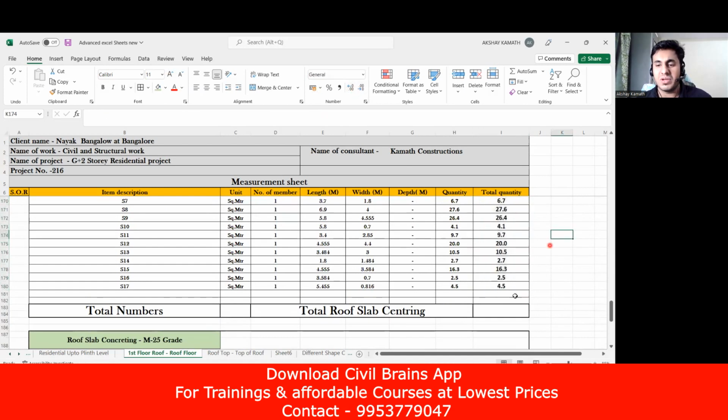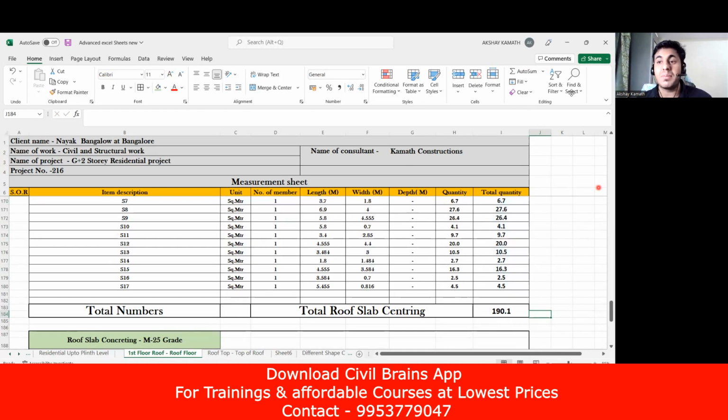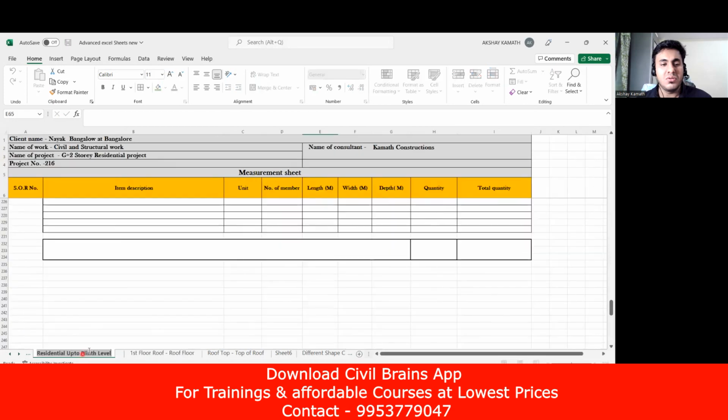Fine. So here keep your mouse and say auto sum and enter. Done. 190.1. Make it bold and bring it to the center. Finish. So the total slab centering quantity I require is 190.1 square meter. And if somebody asks you how much centering plate is required, just understand what we had done previously.